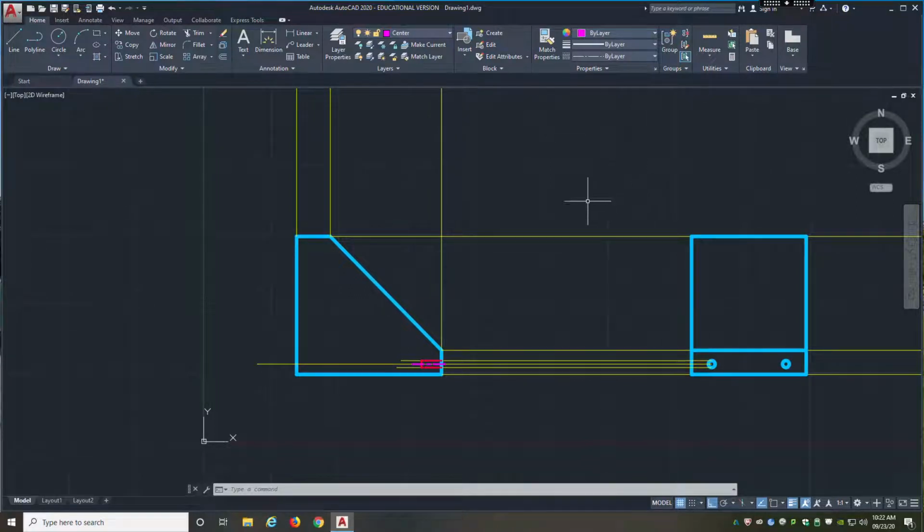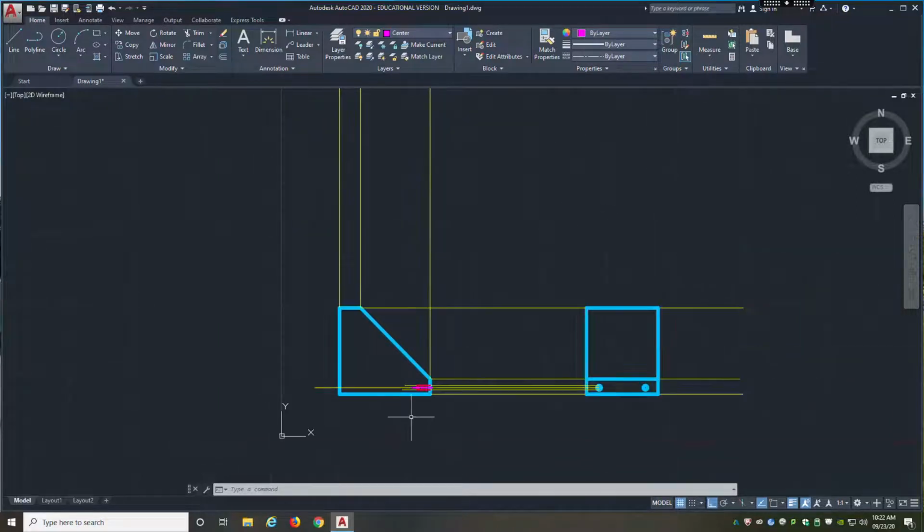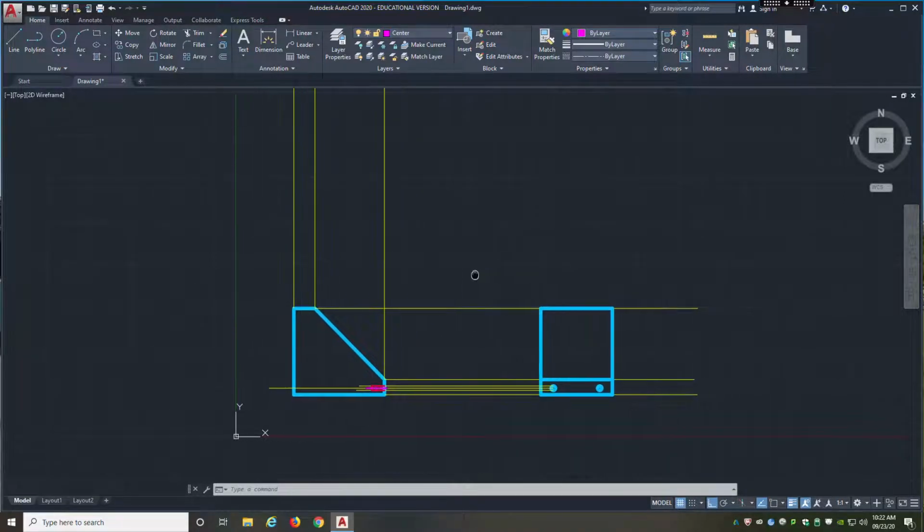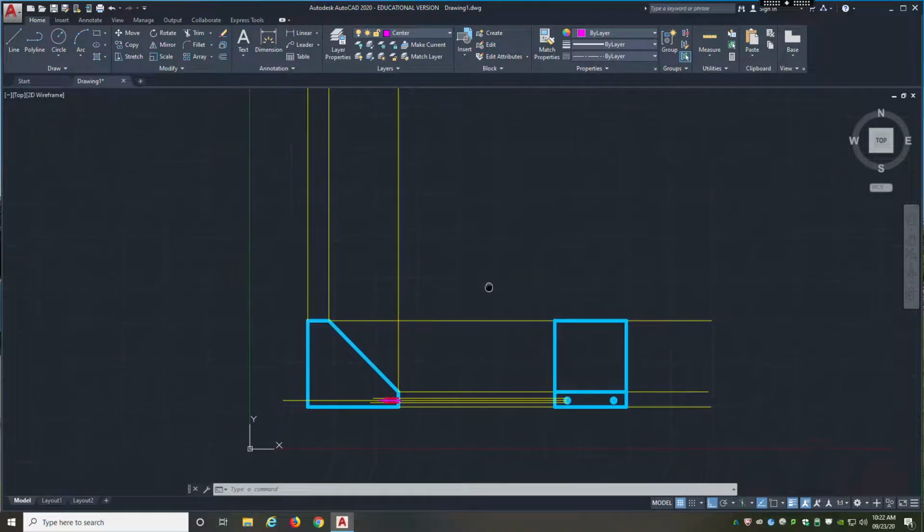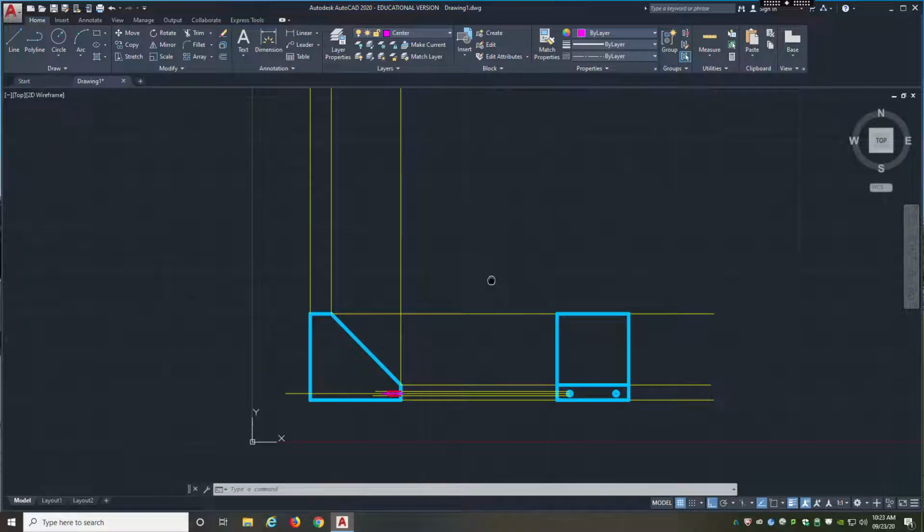Okay, so in that drawing we have an auxiliary view, and the auxiliary view is something that you guys should be learning in print reading for this week. So the auxiliary view can be placed. It has to be aligned with this incline, this line here. And as far as where it goes, it doesn't really matter per se, but it'll help us with the alignment.